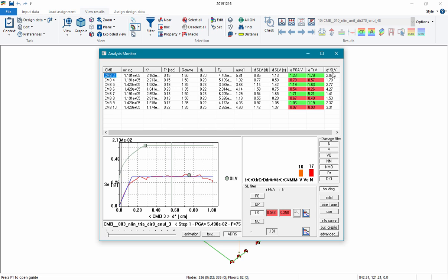The last data in the table is the ratio between the acceleration in the structure with unlimited elastic behavior and in the structure with limited strength. It's data required by Annex B of Eurocode 8. So you can refer to this regulation for further information about this data.